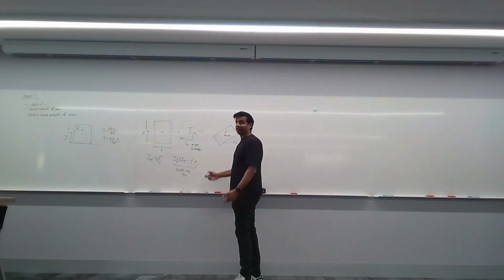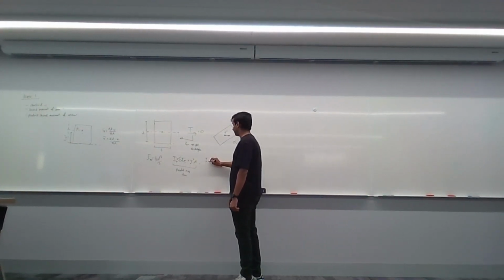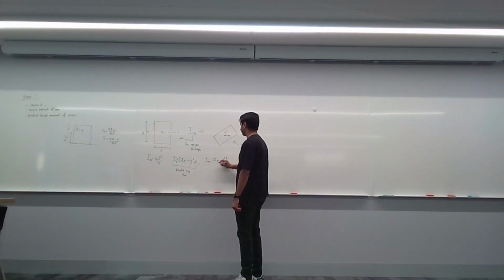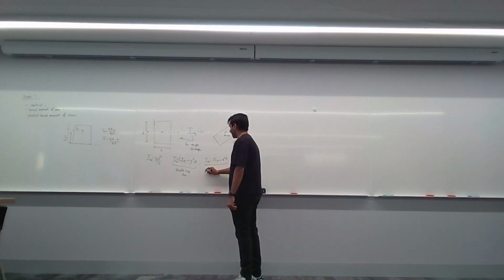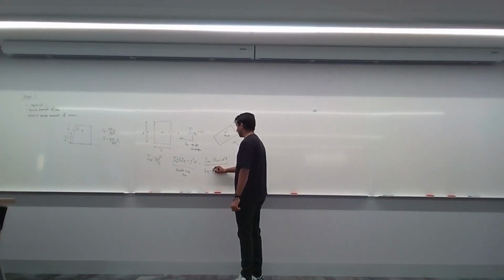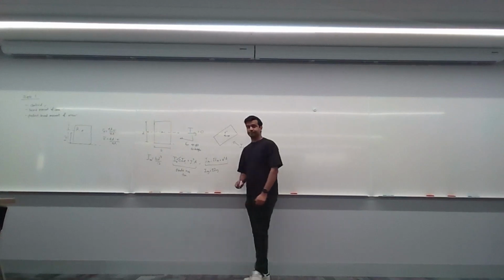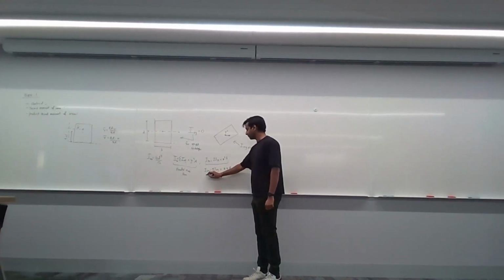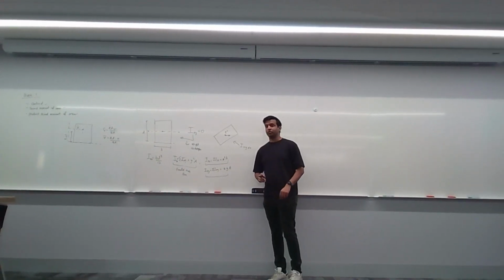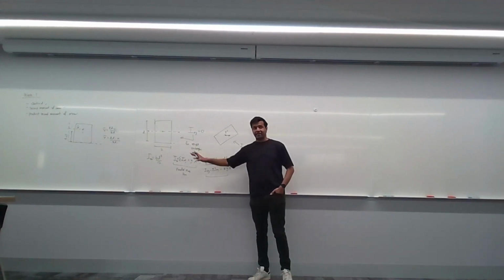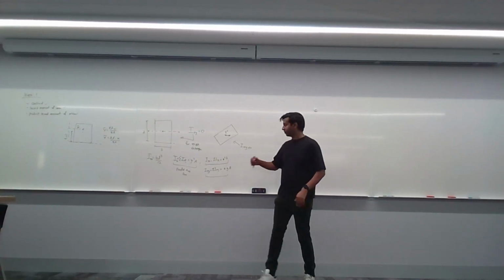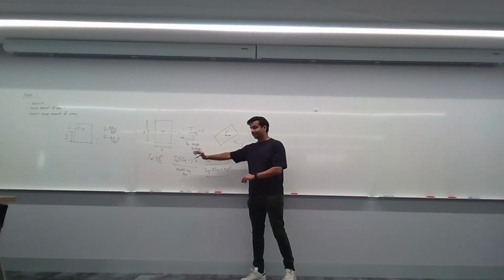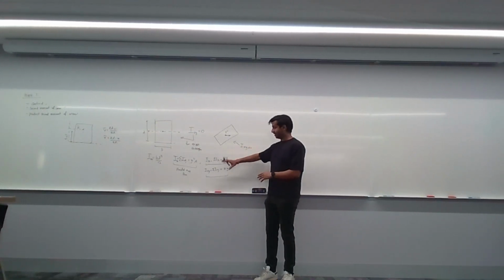The Iyy parallel axis theorem is Iyy equals the sum of all individual Iyy's plus x squared A. And Ixy is the sum of all individual Ixy's, right, plus xyA. So this is all the parallel axis theorem, just with reference to different axes. For Ixx, that's the parallel axis theorem. Iyy, that's your parallel axis theorem. And this is for Ixy.